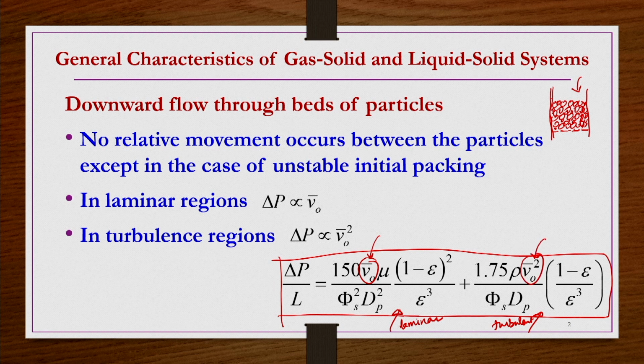Okay. Now, let us say same packing, we take a column, now we pack it with a certain kind of packing material, spherical particles or short cylinders or Raschig rings or crushed glass or whatever irregular particles you want to take, you take and then pack them. Now, here also we will not have any kind of constraint or closing at the top, confining the bed at the top.